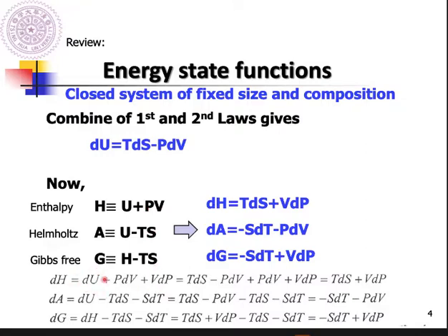And here dU, you already know, equals T dS minus P dV. You just copy the rest of it, then drop the same terms here. So you get dH, the change of enthalpy, equals T dS plus V dP. So the change of enthalpy is related to the heat and also the mechanical work